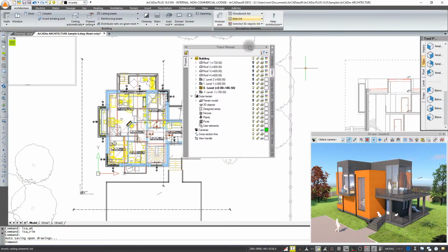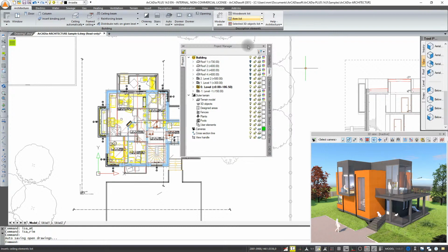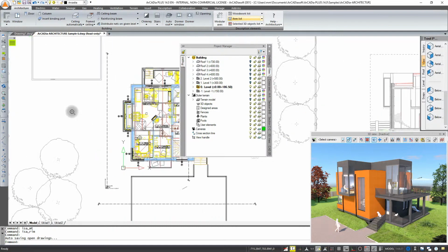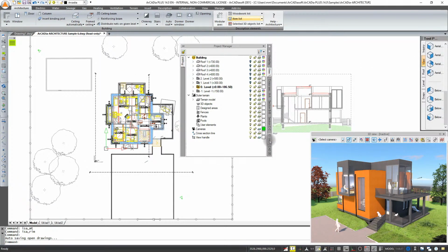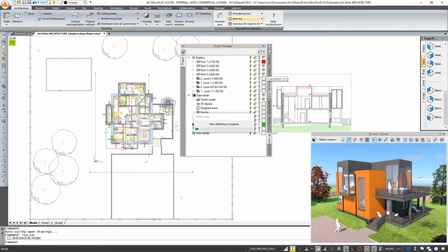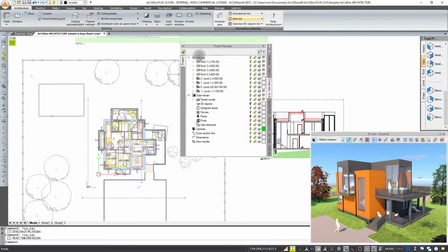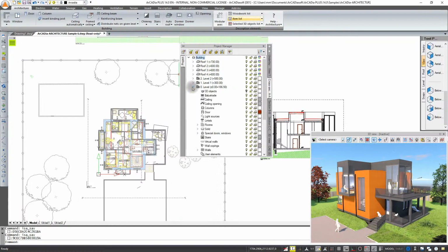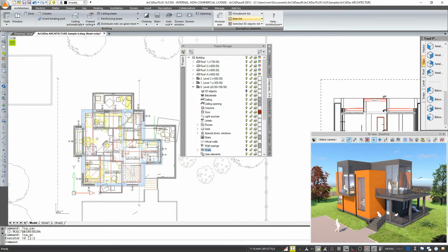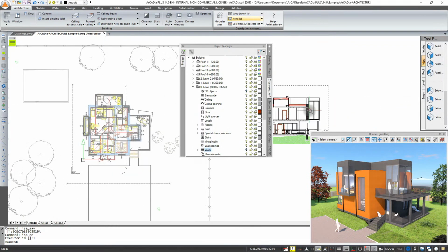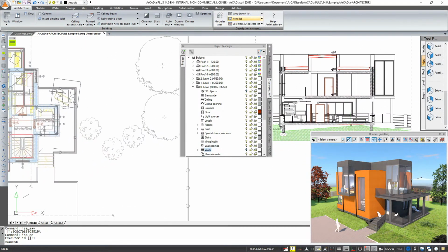It manages our project. It manages all the views, as you can see here on the right. All views that are in the program, you can switch between the views. You can see the cross-section, 3D view, 3D CAD view, that was shown here. So the project manager is used to switch between views, create these views, but also, as you can see here, to manage what is visible. So I can, for example, turn off the walls here. Some of them are obviously visible in the CAD 3D view, so some things are left here, of course. But I can still see that there are hatchings that have disappeared. So these elements have been turned off from the view.